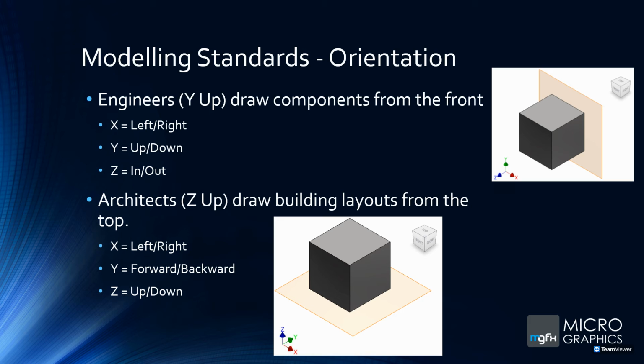So what you need to do is just keep in your mind exactly how this thing is orientated when you do start working. And you'll see there that you've got your origin work planes. I'm going to talk about that a little bit later, but rename your origin work plane so that you know exactly which plane to start working with and which is going to be the top part of your model.